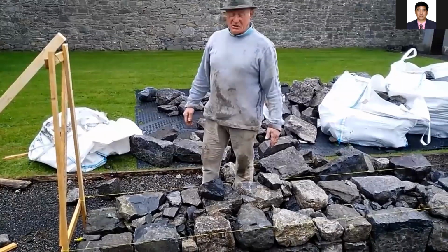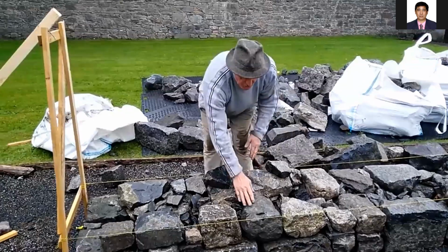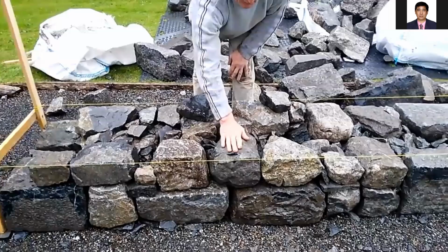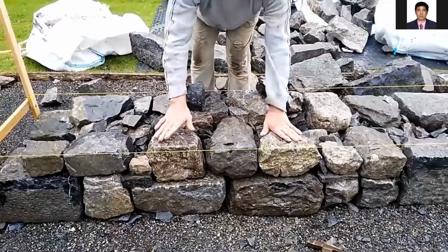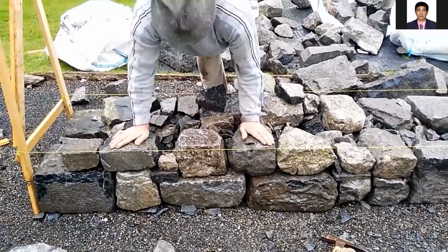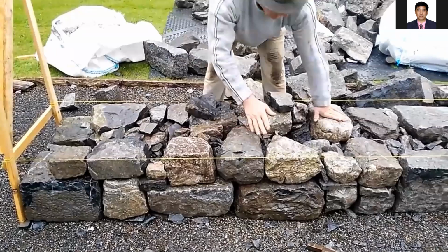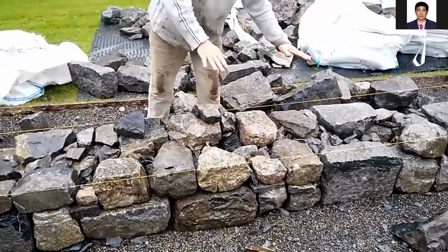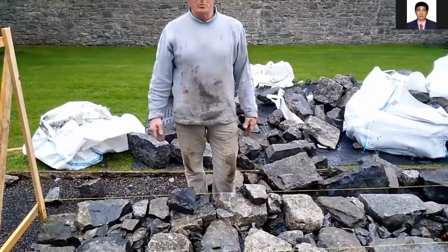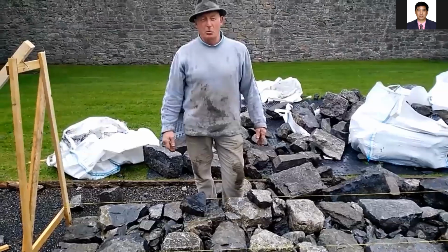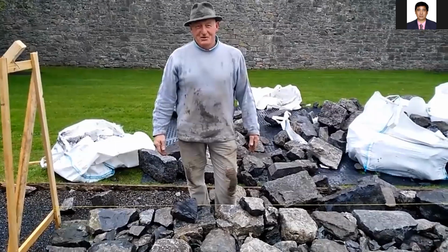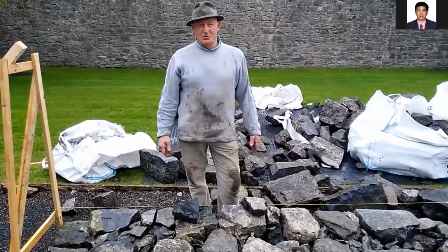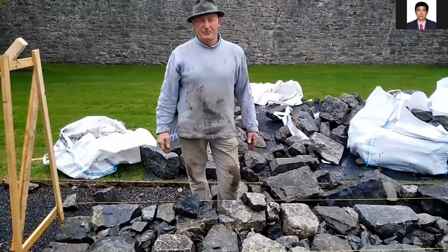That's what it is. You try and cross every joint, and you try and keep your stones as level as you can. It should be solid like that, none of them rattling, and everyone's solid. You have flat stone, you have round cobble, wherever you come across, you have to be able to wall it. You use the materials that are available in the area.